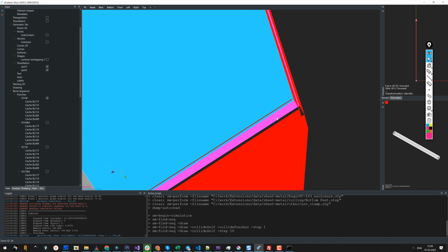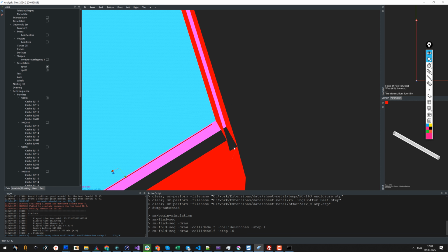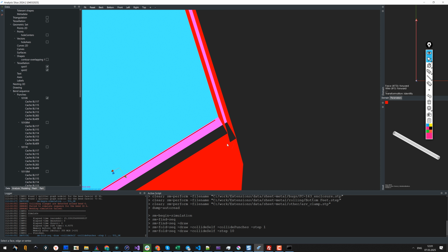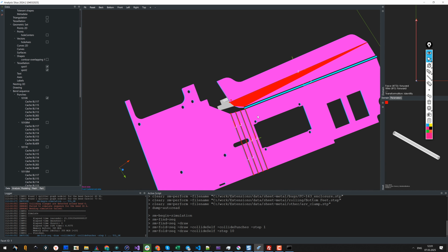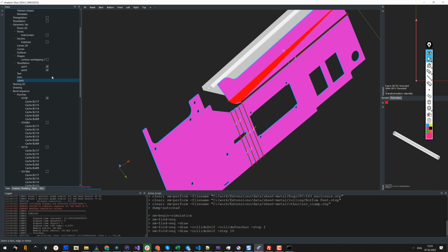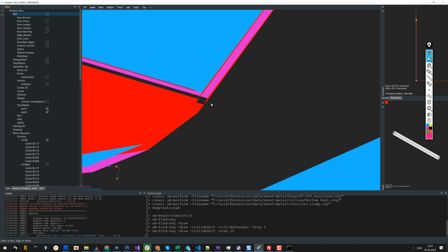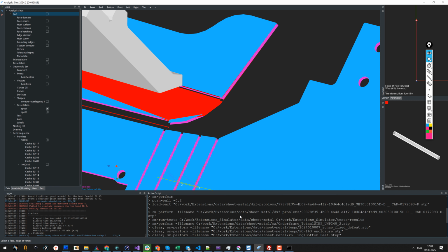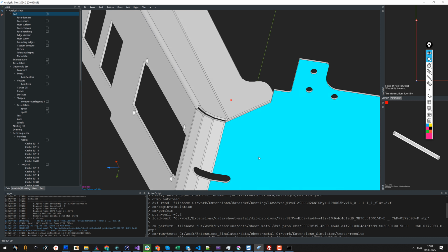So here what happens is that the part starts to intersect itself, because this spike here touches the flange next to it, and the software highlights the corresponding triangles, saying okay, there is an issue over here. So what we can do to prevent this false positive, we can come back to the original part and fix it a little bit. So we do not have to come back to the originating system for such tiny fixes.